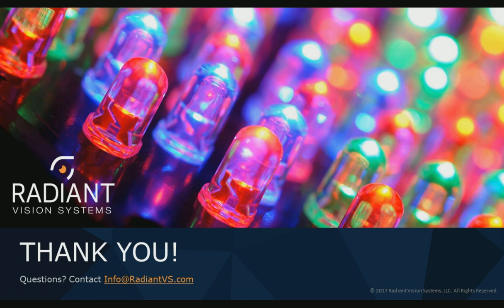So there's a different set of static information that exists within the LDT file that doesn't necessarily have to exist within the IES file format. My guess is that there probably is a translator out there somewhere, but it wouldn't be a simple single-button transition from an IES to an LDT, because there's information present in one format that doesn't necessarily need to be present in the other. So that is a good question, and we could look into that.